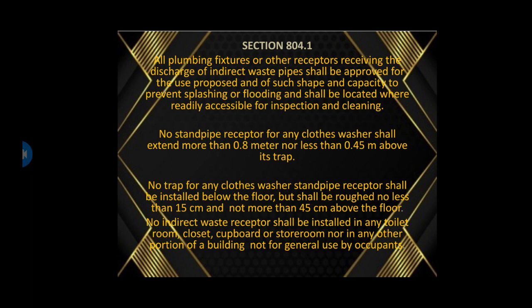Except that a standpipe for a clothes washer may be installed in toilet and bathroom areas in the same room. No standpipe receptor for any clothes washer shall extend more than 0.8 meters nor less than 0.45 meters above its trap. No trap for any clothes washer standpipe receptor shall be installed below the floor, but shall be roughed in no less than 15 centimeters and not more than 45 centimeters above the floor.